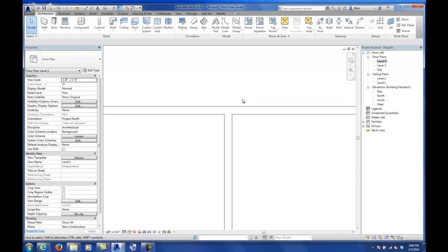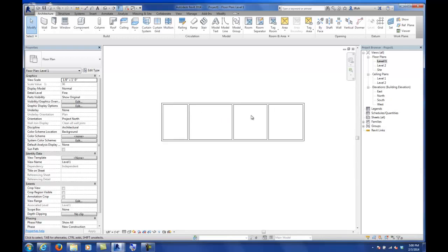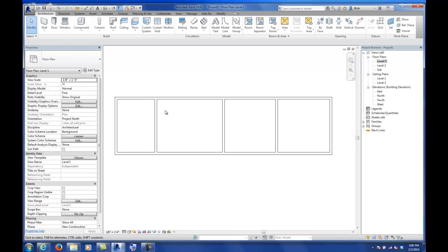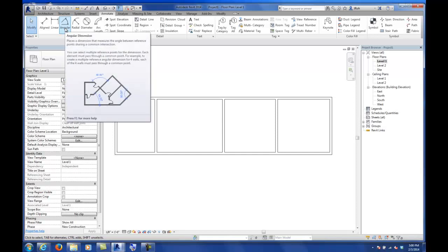So those are starting to get into a little bit of level of detail that we'll start to see in other wall types shortly. But one thing that we can do with drawing in Revit is we've used the temporary dimensions. Another component to Revit, and especially modeling, is that under Annotate, we can use actual dimensions that you would typically see on a piece of paper. We can actually use those to also set constraints and set particular equality constraints or locked constraints to our design.